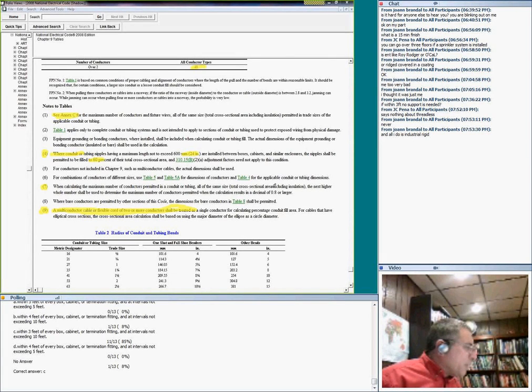These are important. There is another one that I always highlight, Note 7. Note 7, guys: if you end up with a fraction when you do the conductor calculation, for example, how many conductors can fit in a 4-inch conduit, and you do the calculation and end up with 11.8 conductors, that will make it 12.